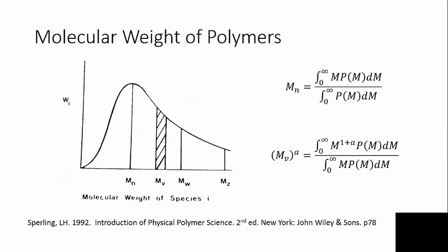In part 2, you're going to look specifically at polymers. We said these viscous materials may or may not be polymers. We're going to look at polymer solution, and we're going to look at the viscosity because we want to know the molecular weight of a polymer. Now, many polymers are made in such a way that they are polydisperse. So here we have molecular weight, and there's a range of molecular weights, and the number of molecules that have a particular weight, we could have a distribution like this.